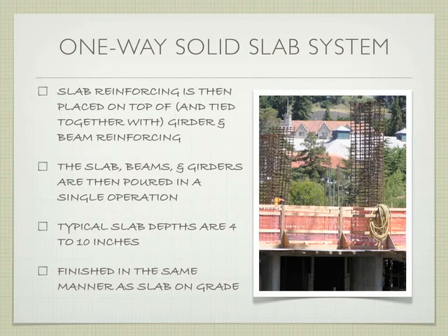And then a typical slab is going to be somewhere between 4 and 10 inches. Obviously, if you're in a parking garage, thicker slab, more weight. If you're in something that's residential, maybe you can shrink it down. It's also dependent on the length of the span. How far is the span? The longer the span, the deeper the slab. It's finished in exactly the same manner that we talked about doing a slab on grade,